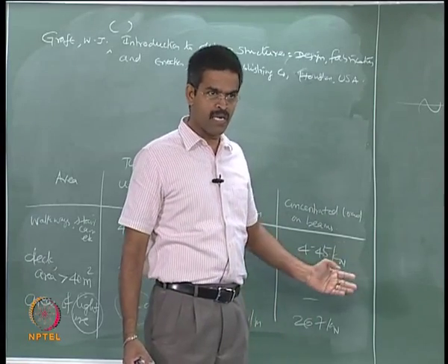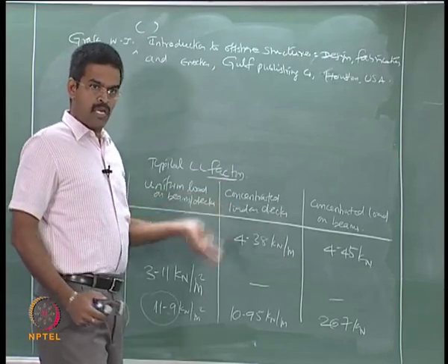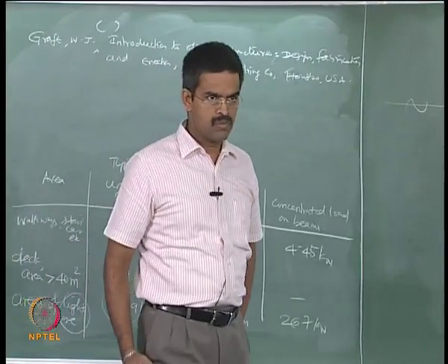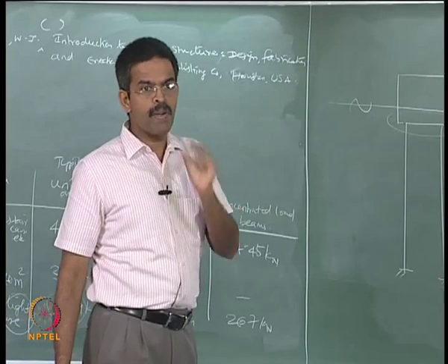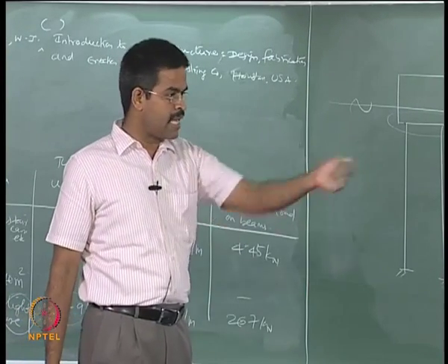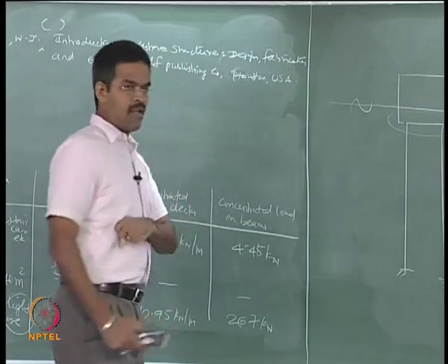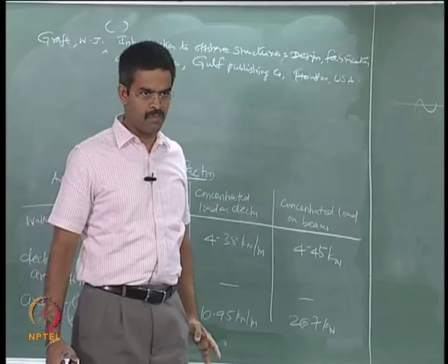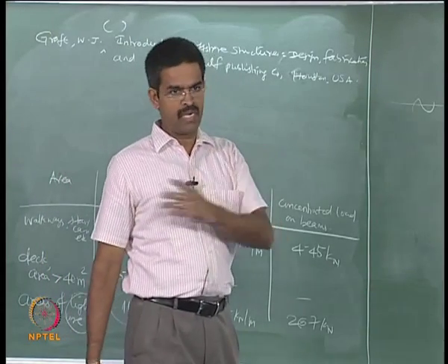So people have said, let me multiply these live loads with a factor to create an impact load. So I am looking now for impact load factors. Impact load is not essentially arrived at directly from any equipment; we simply pick up the live loads and multiply them with a specific number, what we call IL factors, impact load factors.